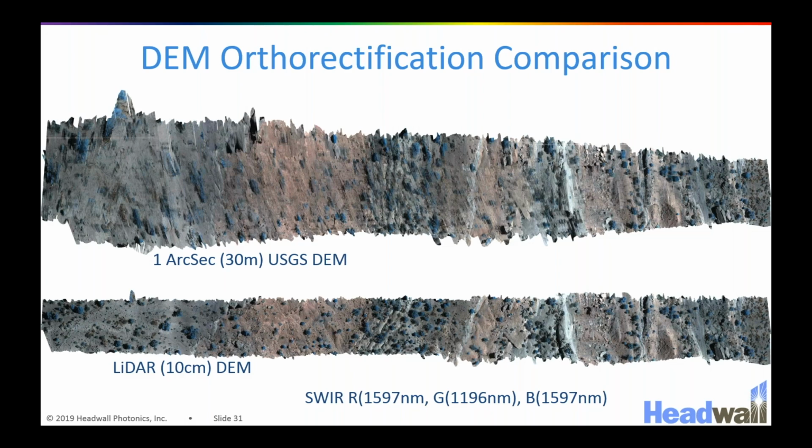The other question is, once the flight plan is set, does the drone fly the pattern to acquire the data? And the answer to that is yes as well. Through the flight planning software, the UgCS flight planning software that we use, you can set a flight plan, and we of course always recommend that you pre-program a flight plan and have the drone automatically fly it rather than trying to manually fly it, because the computer will always be better than you.